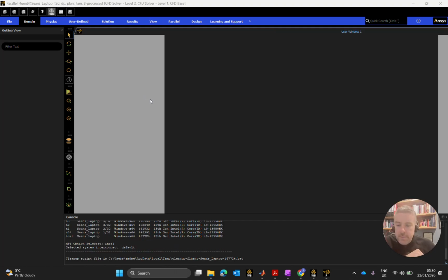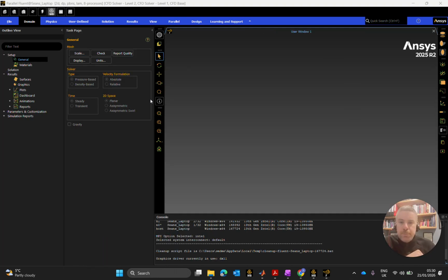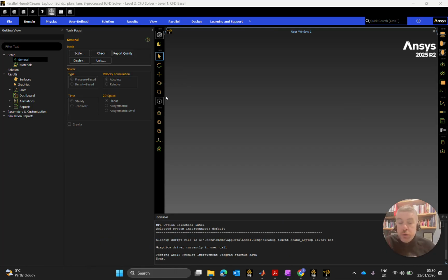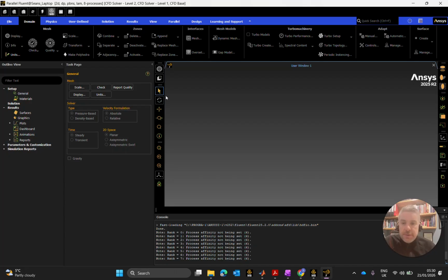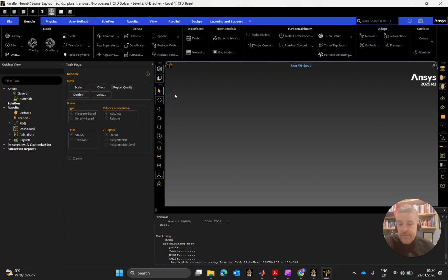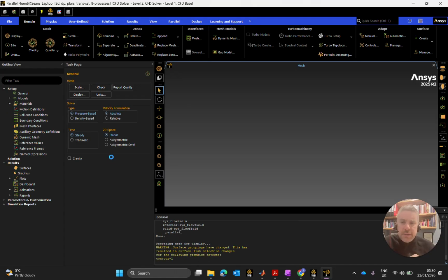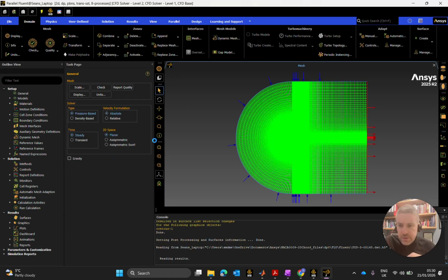Right, so the first thing I'm going to do is ensure that I have given Fluent enough iterations to ensure that they've converged. Now, I think that I have. Okay, I don't think that I have currently set up 600 maximum iterations in this. I don't think I've ever gone as far as 600 iterations.